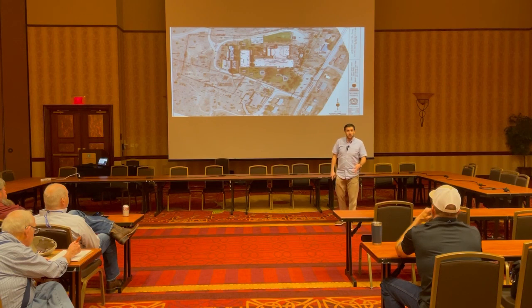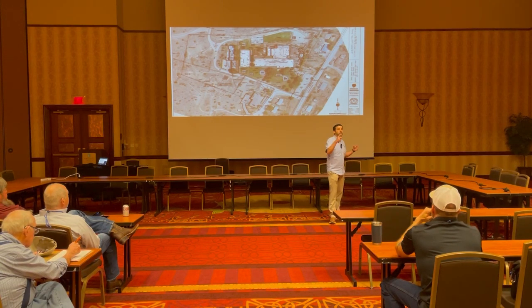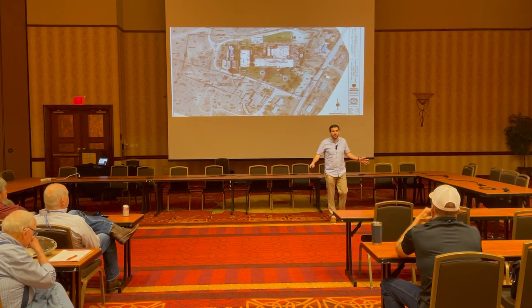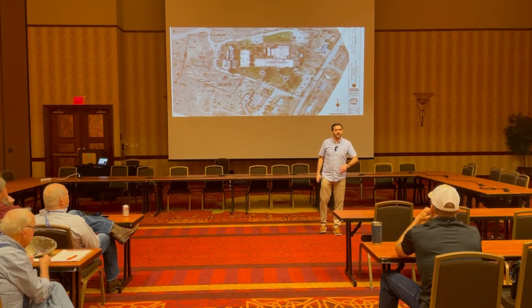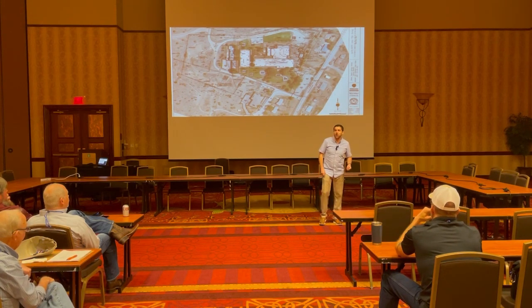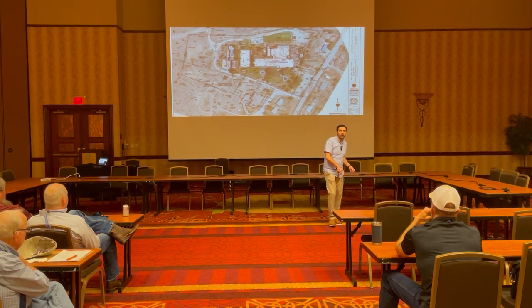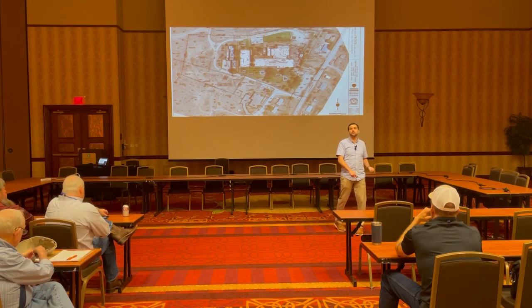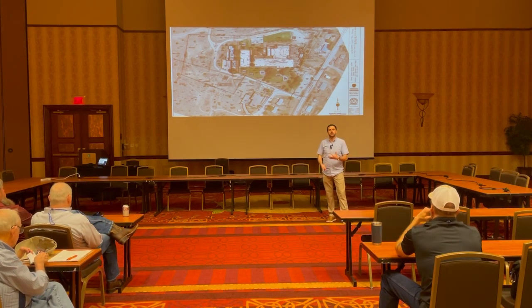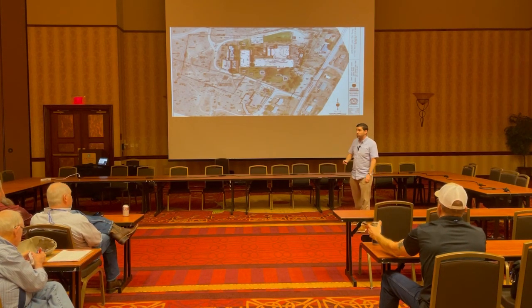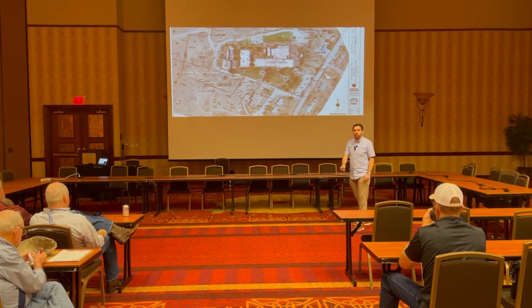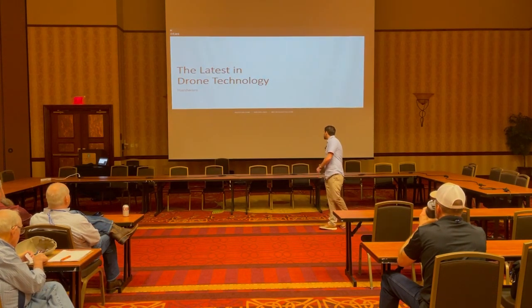Because I don't know about you, but very, very few clients ever raise their hand and say, hi, I'd like a drone survey of my property done. They say, I want a survey done. I want this data. You figure out how to use it. In the same way that some clients might specify the tools needed, but it's up to you as a surveyor whether to use a GPS or a total station, or whether you're correcting based off of a network correction service, or you set up a base and do an OPUS solution. There's so many ways to do it, but it's up to you to choose the right tool. And that's what this is about, is choosing the right tool to get that survey. And the drone is an excellent tool that should be in your toolbox, even though it's not right for everything.